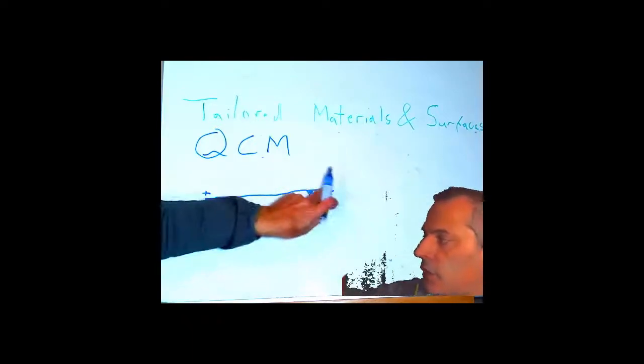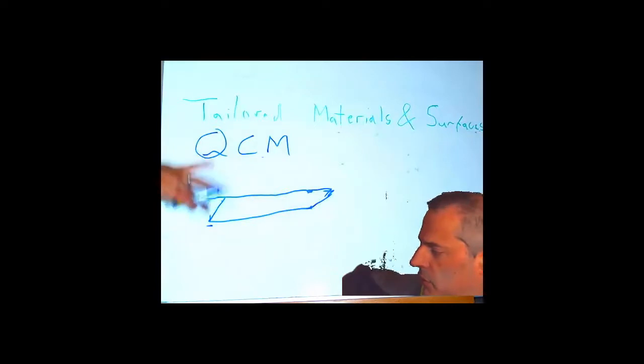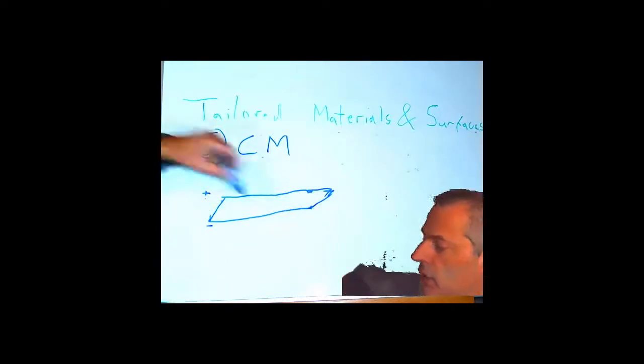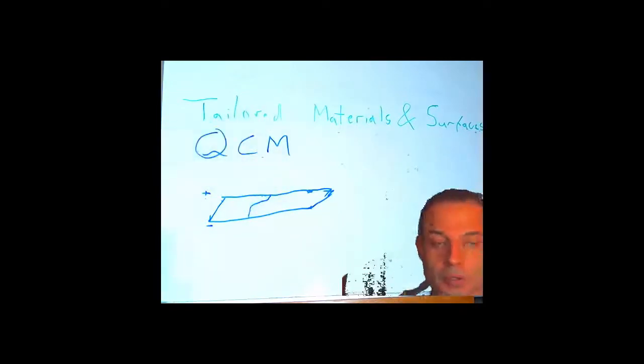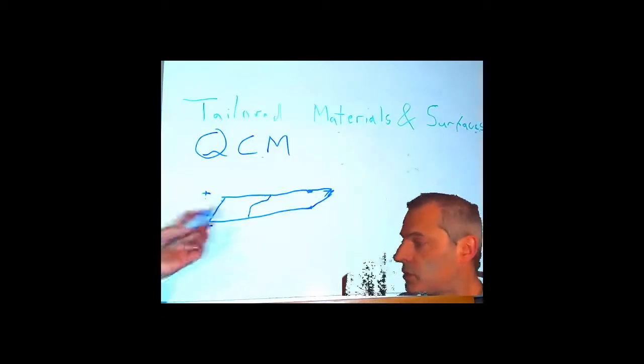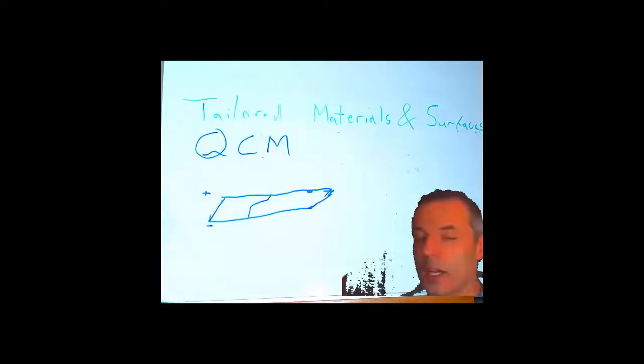The interesting thing about these is that they have a fundamental frequency, so they have a frequency they like to oscillate at, where one wave of a sound effectively fits inside the crystal. That is why they're used for timing devices in computers and clocks, because this frequency is relatively exact, much more exact than normal electronics can be, and then it can be used to count, to keep things on time. A typical quartz crystal microbalance would be running at a few megahertz, somewhere between 5 and 20.